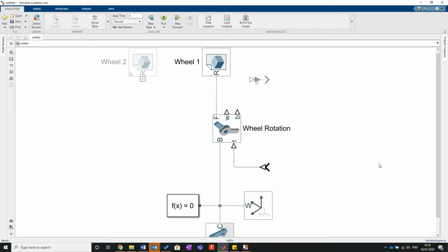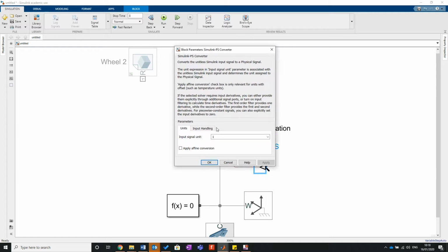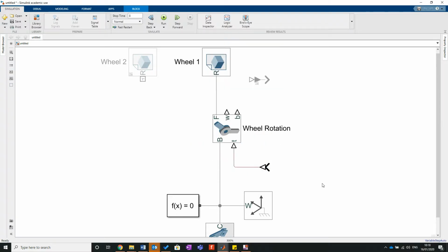Now, we know from the notes or the configuration system that we need to be operating in Newton millimeters. So in my signal input, I say Newton. Now the beauty is you'll notice beneath it says Newton times M. So it's already showing you how Newton meters is represented in this input box. So you can instantly presume Newton millimeters is represented similarly. So click apply. Now we know that we're in the correct format.